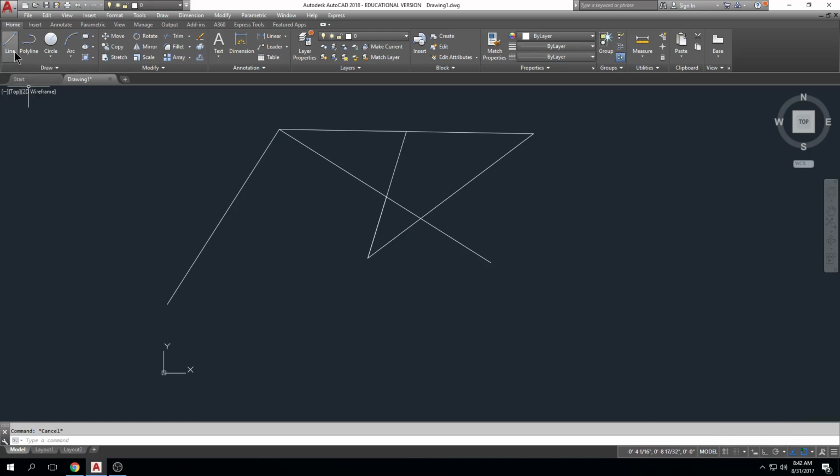I come up here, I initiate the line command. I come down here to ortho, click, I turn it on. I click in model space. I move in the direction I want to go, and I start drawing straight lines, right? And you'll notice that wherever I am in model space, that line is straight. It's being constrained, okay? So unless I object snap to a line, see, even then it's having trouble. It doesn't look like it's going to draw to that corner I'm touching, but it will. Click. Okay, so I kind of have to snap to override that because just by default it won't draw lines that are not straight.